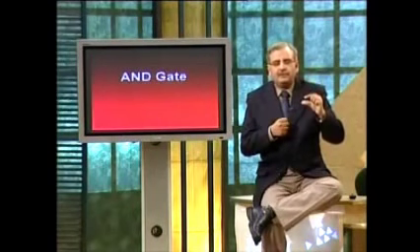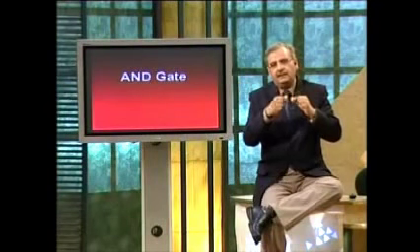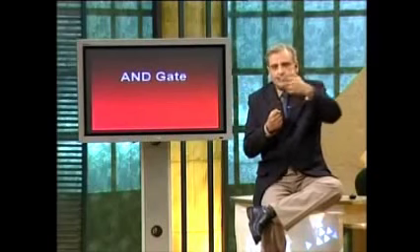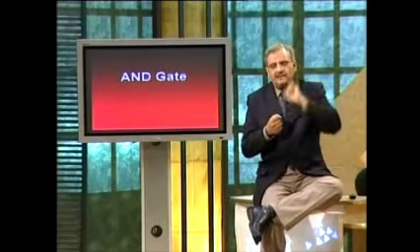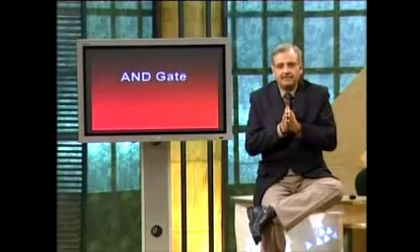The thing which I forgot to tell you, there is an alternate symbol which represents the AND gate. It is a square with one pin at the output, which indicates the output, and 2 lines at the input side. Within the square, you have an ampersand symbol, which basically indicates an AND gate.